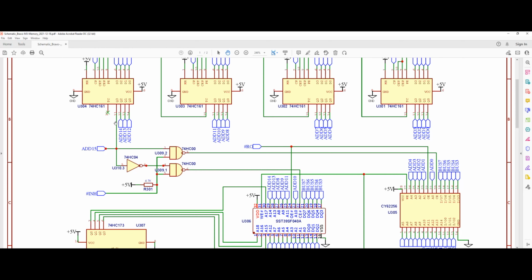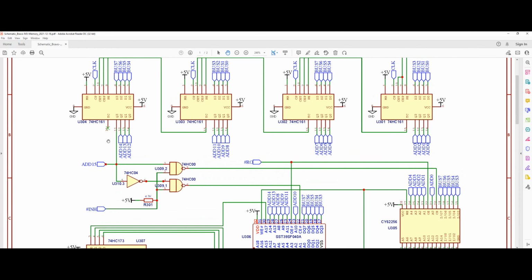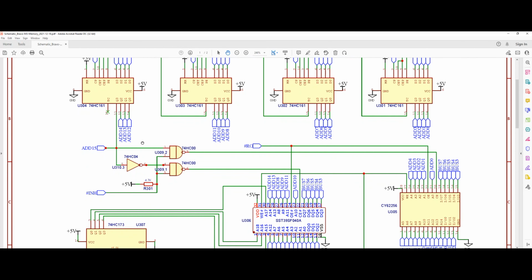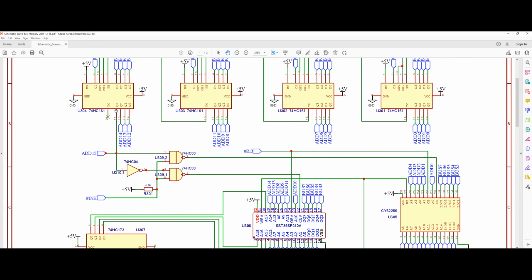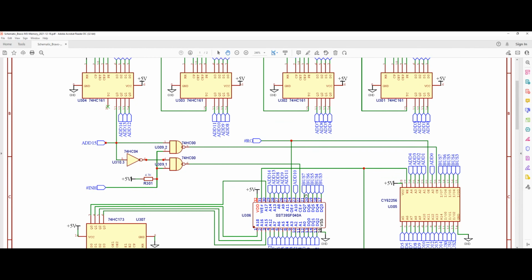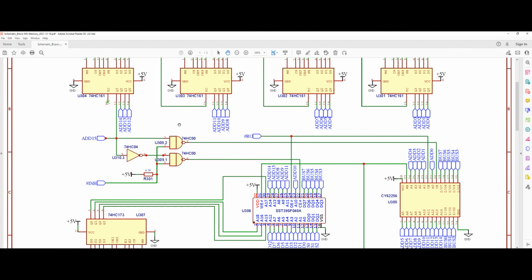Now, the last line, or let's say the most significant bit in our memory address register output, which is the last pin here on the last chip, is actually a chip enable signal, meaning that we are not using that last bit for addressing here. We actually are using this signal as an enable or disable signal for our chips. So let's see how it happens.